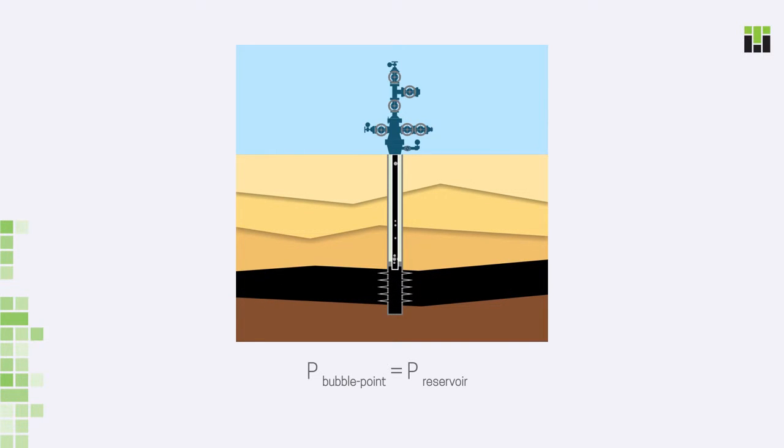In some cases, gas does not come from solution while oil is in the reservoirs. But as the oil goes out the wellbore, pressure falls down. Then they reach the bubble point, gas starts coming out of the solution and helps lifting the fluid up. This technique is the cheapest one, as it does not require additional energy that would lift the fluid up to the surface. Besides, it does not require special equipment, which is expensive and requires maintenance.